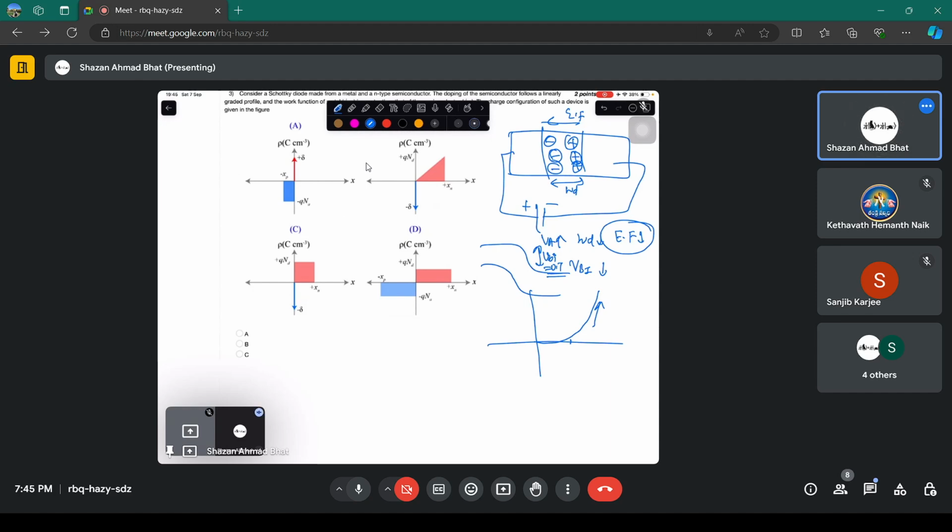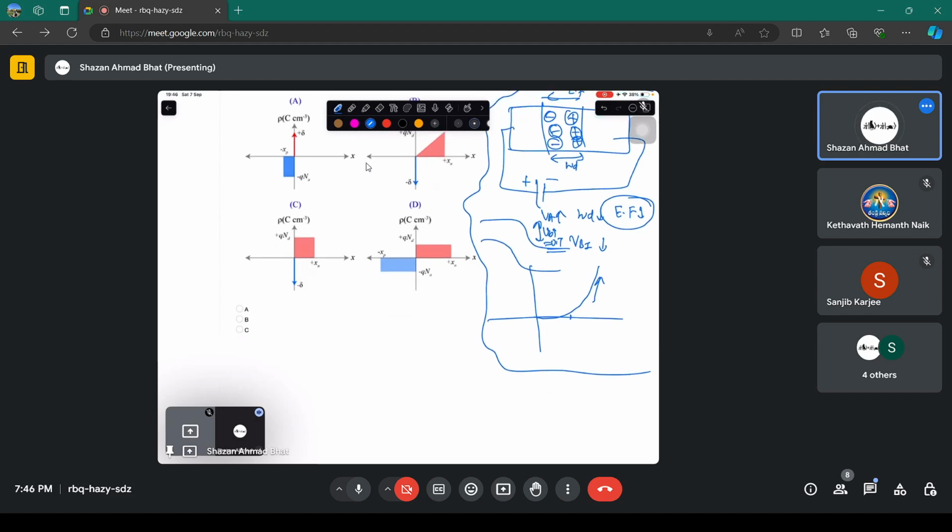The only thing you can measure is when you apply current to it, that current flows, and then the potential across it you can measure. The internal potential, you cannot measure it. Just remember this point always, because that's mostly a misconception among students, and that's mostly asked in interviews. It doesn't matter whether you are applying for jobs in industry, or even as an assistant professor at universities or colleges. This is the fundamental question that's asked.